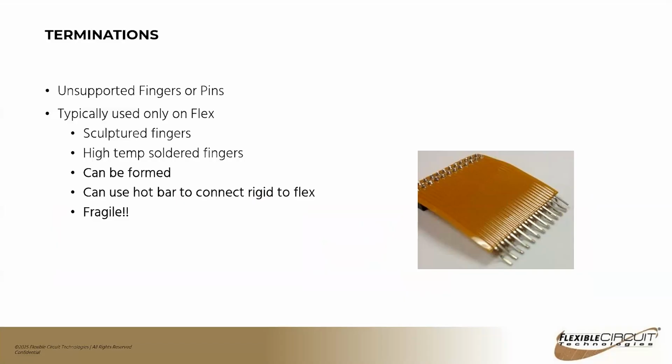Another option is to actually have a comb connecting all the fingers, and then those could have pin holes in them that allow you to fixture them, get it in place, do your solder operation, and then snap the comb off.